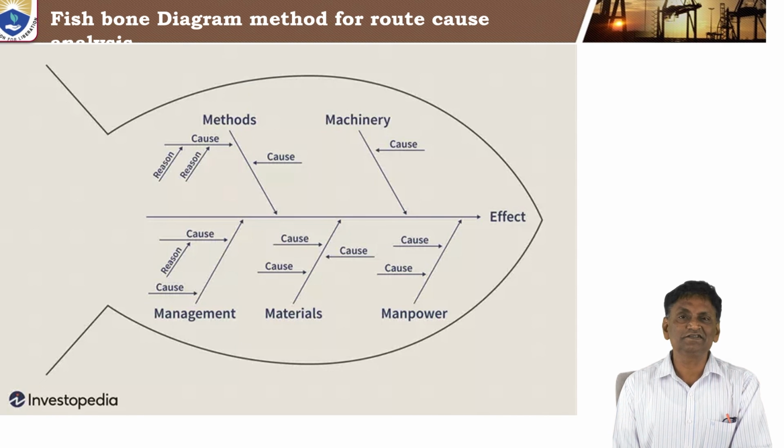Then the other thing is they were not using the right materials to do this job. They were not using the particular grade of steel which is malleable and easy to cut and has the properties, but they use some other harder material. That's why tools are damaged and the machining is not proper. So materials were not right, or the materials were not suitable for the temperature at which it is exposed to during the machining.